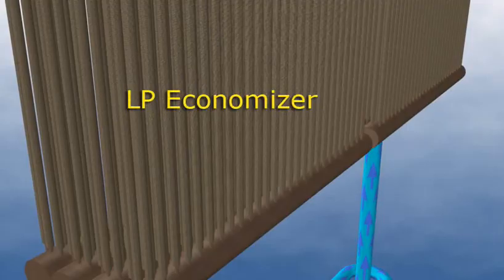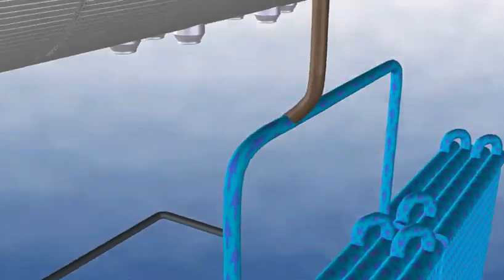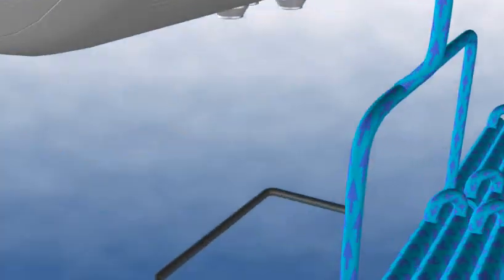The condensate flows through the LP economizer to finally discharge into the LP drum. During startup of the unit, condensate can be recycled through the economizer by means of a condensate recirculation pump.